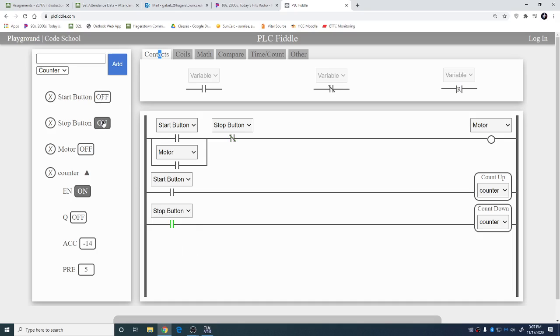But you notice on this one, you see how it's constantly counting? Allen-Bradley has this same issue too, actually. If you try to do a count up, down, they don't exist in Allen-Bradley world. You don't have the option to do both, which kind of annoys me. But if you notice, this one's constantly counting. Allen-Bradley does it a whole lot quicker, again, because the program's running a lot faster. So this is kind of showing you the loop time, basically. All right.